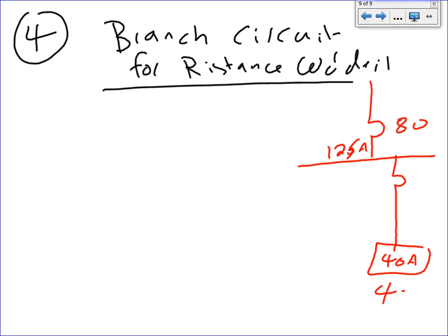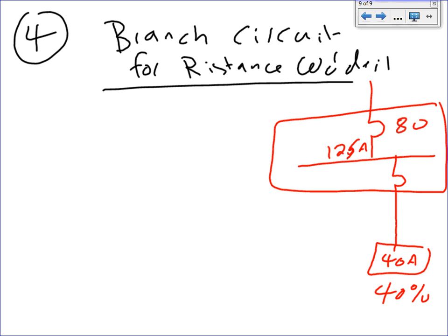Okay, so here's what I'm sizing, guys. I have my main panel. I'm pulling a conductor, and I need to size the same thing. Number 1, number 2, and guess what? I'm going to go all the way here to ground, and I'm going to pull number 3. I'm sizing 1, 2, 3: the phase conductor, the overcurrent protection device, and the equipment grounding conductor.